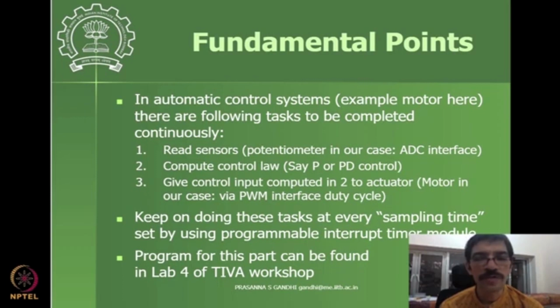Only the functionality which gives you the handle over the PWM duty cycle can come in the interrupt service routine. Like that, you think what will be coming from the encoder interface into your first part, reading the sensor. You need to start thinking and programming like that.